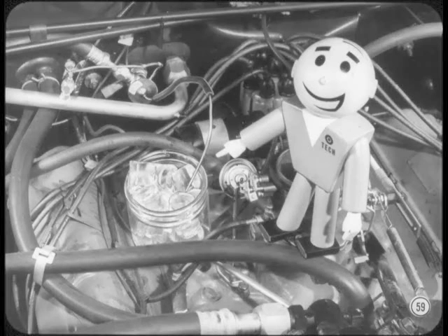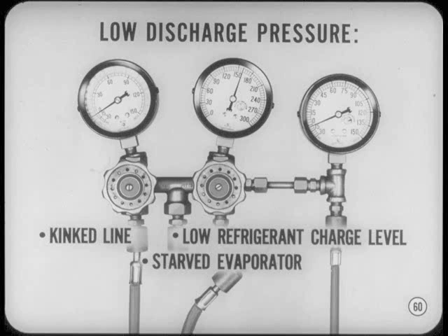Fred will tell you what to do about that further on. Right, Fred? Right, Tech. Now, at the other extreme, if discharge pressure is lower than normal, it's usually a sign that the evaporator's not getting enough refrigerant. Here we may find a kink in a line, low refrigerant charge level, or a starved evaporator.